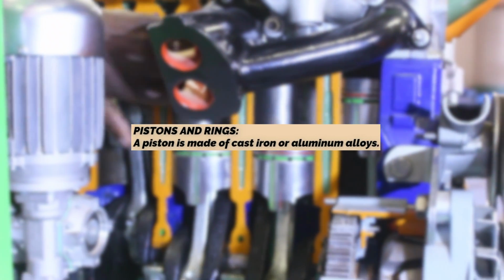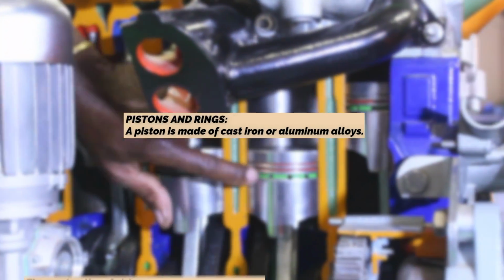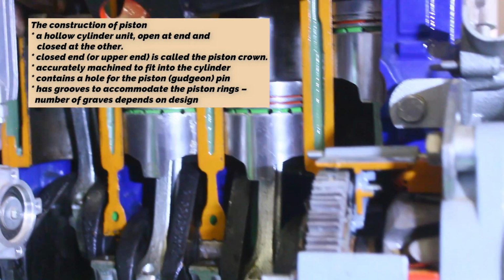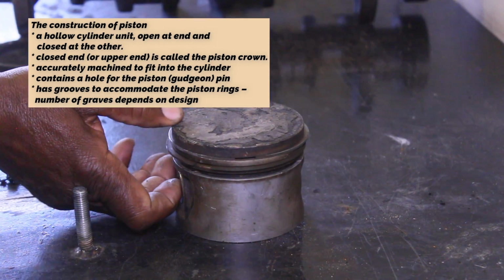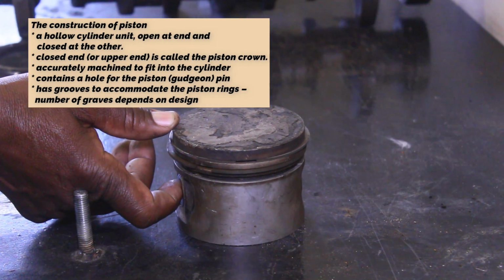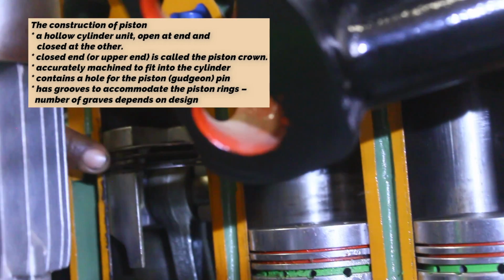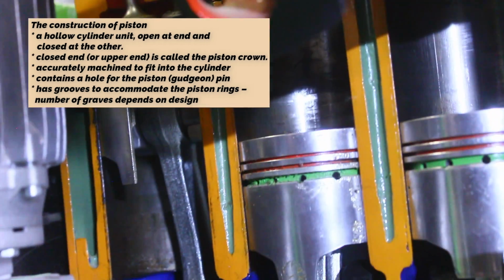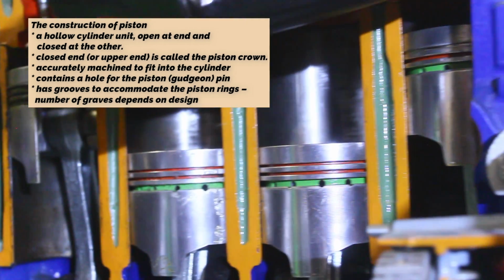Pistons and rings. A piston is made of cast iron or aluminum alloys. The construction of a piston: a hollow cylinder unit open at one end and closed at the other. The closed end or upper end is called the piston crown, accurately machined to fit into the cylinder. It contains a hole for the piston or gudgeon pin. It has grooves to accommodate the piston rings. The number of grooves depends on design.